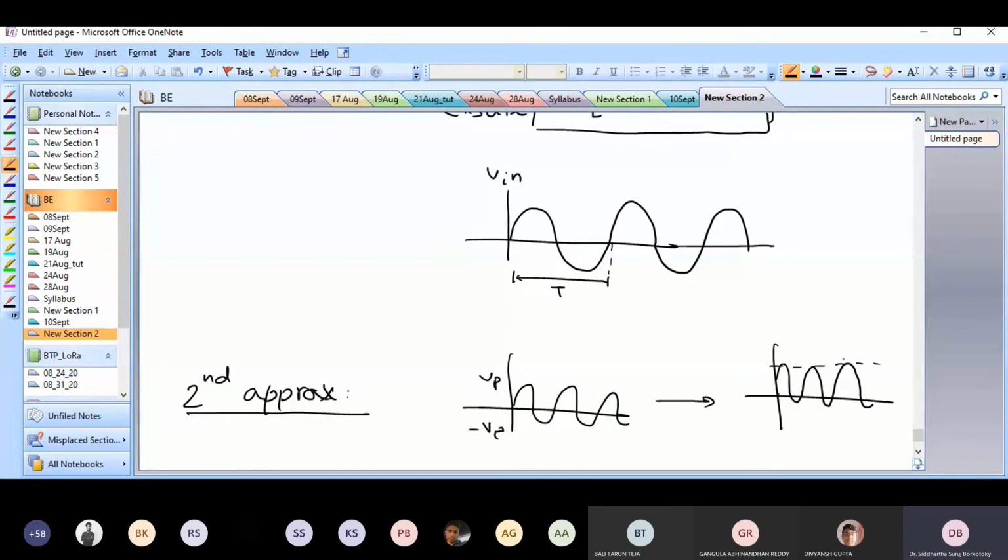So this part will be Vp minus 0.7, and this is 2 Vp minus 0.7, sorry, and this is 0.7. Because of this extra 0.7, you can again justify this by looking at the circuit. But the point is, this barrier potential or the knee potential has this effect of including some offset in these circuits. But as I said, there are techniques to get rid of these offsets.